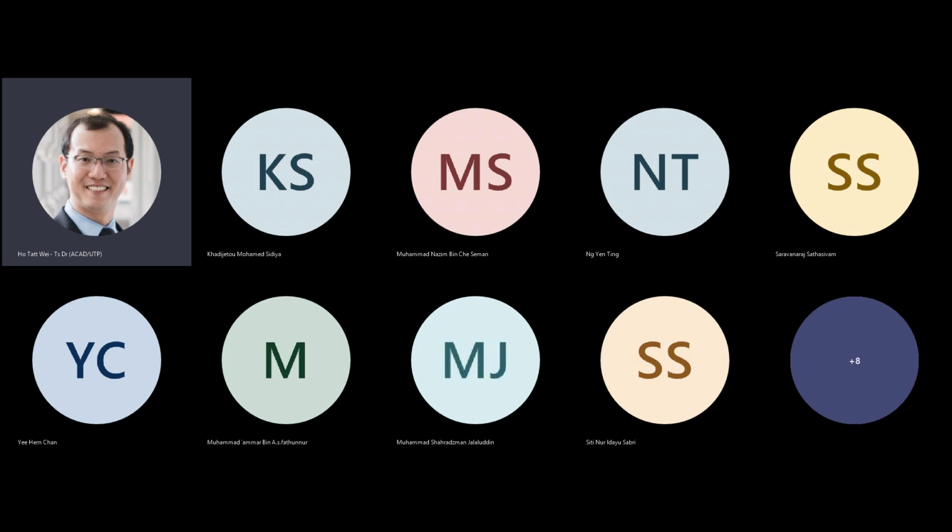I don't really care about this because when this is logic 0, this transistor acts as an open-circuited switch. So whatever voltage is sitting here does not get transmitted here. Only this path is conducting. And likewise, when this is set at logic 0, this path is not conducting. There's no channel here. But if this is set at logic 0, there's a logic 1 going out of this NOT gate, enabling the path here, selecting this path.